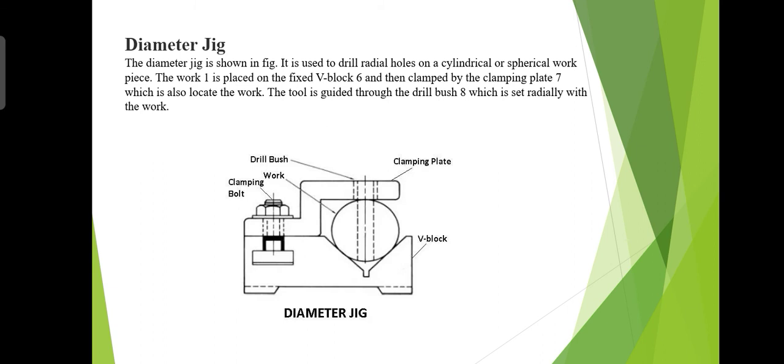Drill bushings are usually located in the leaf. However, bushings may be located in other surfaces to permit work over more than one side, which is known as a rollover jig. A box jig for angular drilling is easily designed by providing the jig with legs of unequal length,